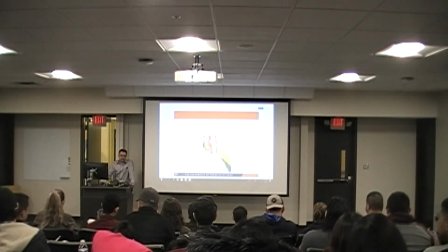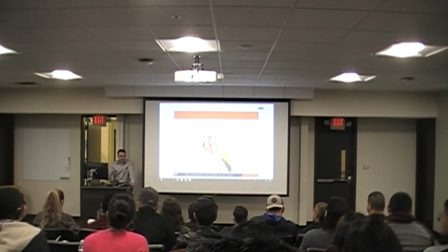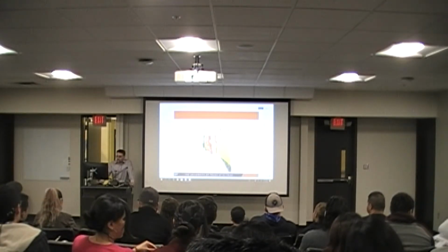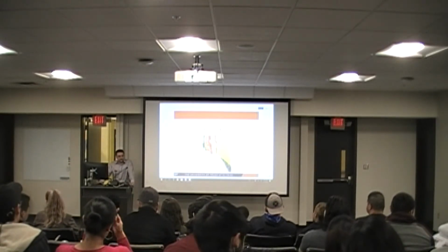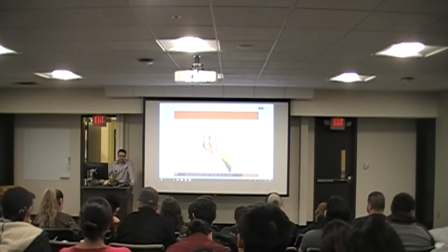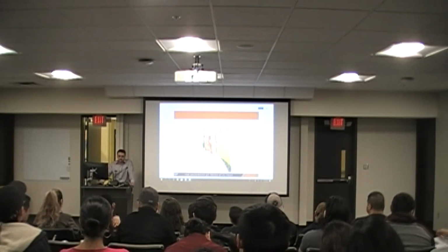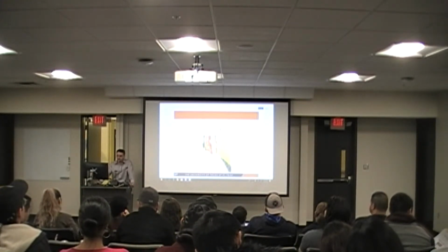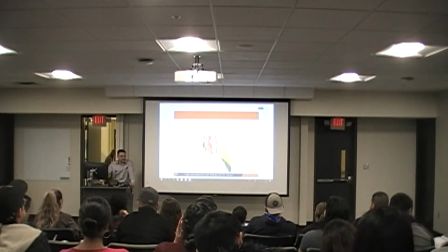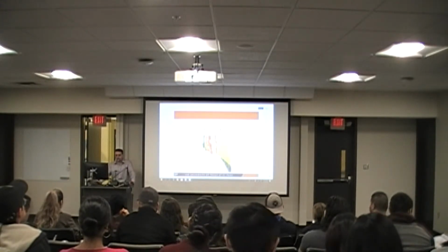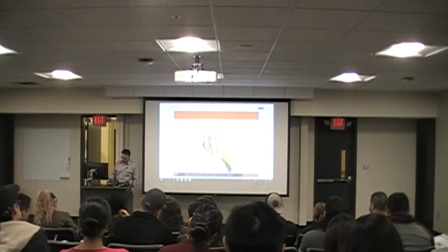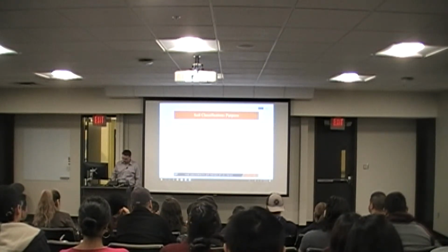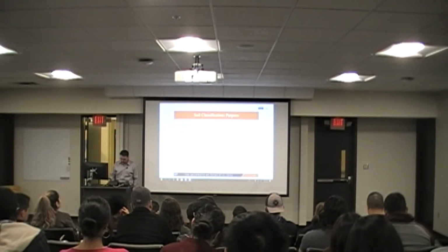We do have the USDA, U.S. Department of Agriculture. As the name indicates, it's for agriculture. The way that they designate the soils, or define the particle sizes, is very different, and also their purpose is very different from ours. So I'm just going to show you how you can classify soils according to USDA. For some reason, in your FE test, you'll be tested on that as well, so that's the reason I covered that in this class. Otherwise, for any other applications, you're essentially looking at the AASHTO and USCS soil classifications.